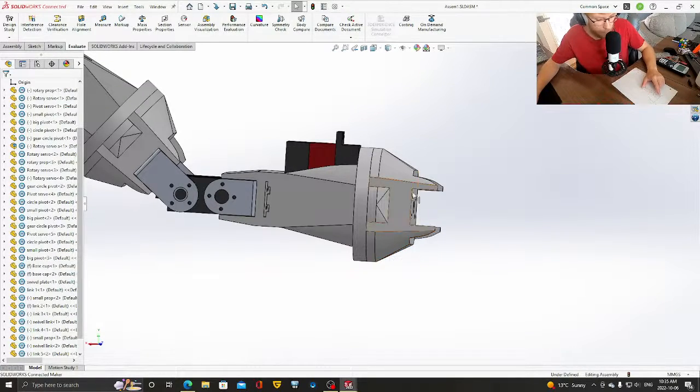Then we'll go up. Probably make the gears 5 mil thick. I think 5 mil should be fine. 10 mil off for bolts, yeah. Make them 5 mil thick. That should be strong enough. Then sandwich on top, I think we'll maybe make something on this gear to help hold it in place better.